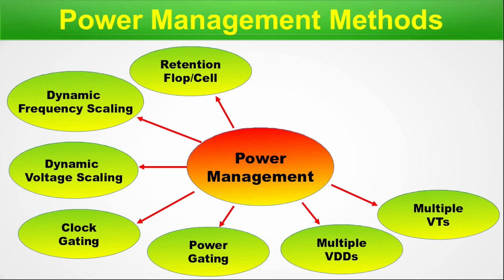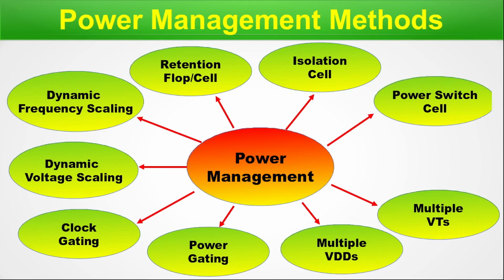From the standard cell families, we use the retention block or cell, isolation cell, power switch cell and level shifter cell. So these are 4 special standard cells that we use for power management. So here the entire picture is clear to you now. So let's move on to the next slide.